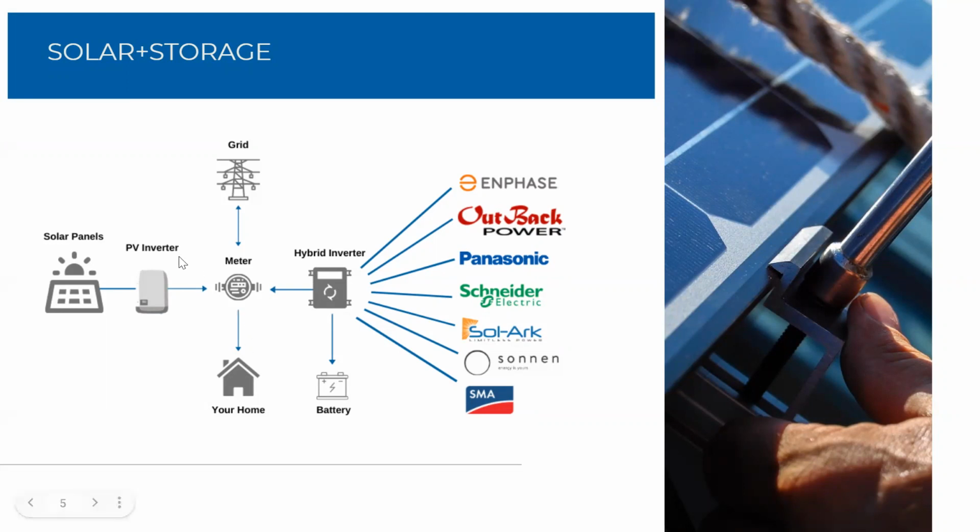So depending on the size of your existing PV inverter, you may have more or less of these options to determine what can I pair with my PV inverter. And we're going to dive into these brands individually, but I want to talk about sizing as a limitation, because you want your hybrid inverter to be equal to or greater than the size of your PV inverter.